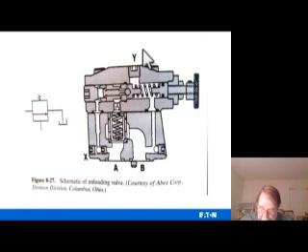And see, this top side pressure on the main poppet goes to a very low value and allows flow from A to B with a very low pressure drop as long as the signal pressure at X is maintained. And then the ball reseats and the main poppet closes with a snap action when the pressure at X falls to approximately 90% of the maximum pressure setting of the spring-loaded ball. And so it's kind of how that works. It's kind of a neat little device, you know.